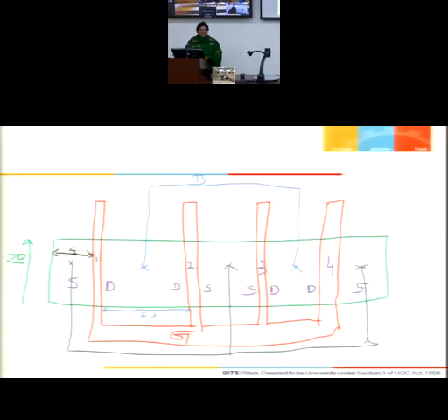By doing the layout very carefully, we can actually reduce the parasitic capacitances. So multiple gate fingered layout is a way to reduce parasitic capacitances, and it is nothing but an approach where we are making a bigger component by using many smaller matched unit components. Many smaller matched unit components. Clear? Is this clear? Yes, Divya?